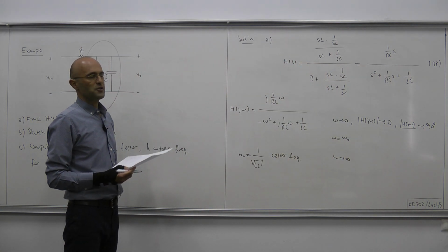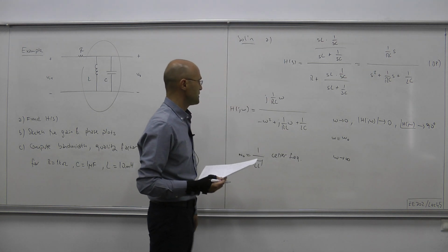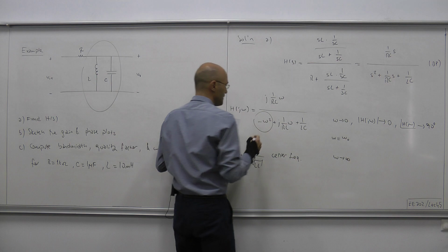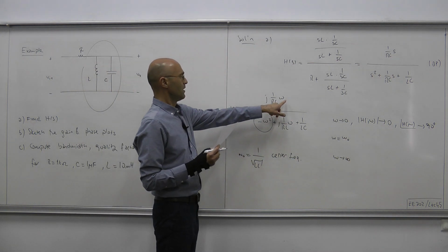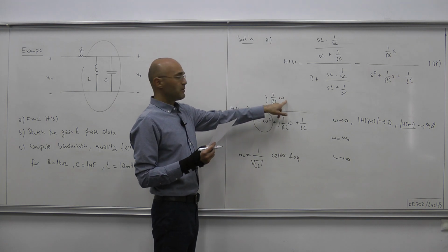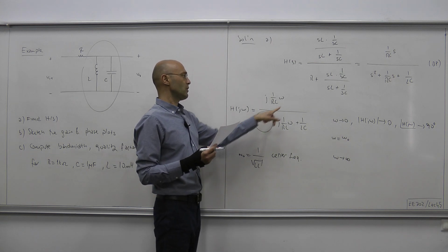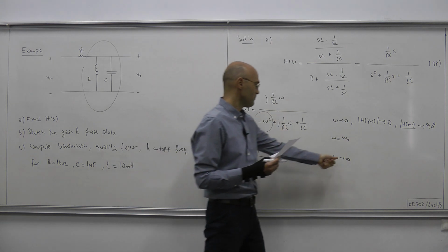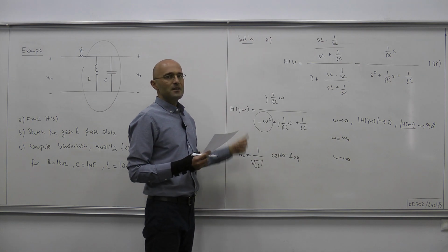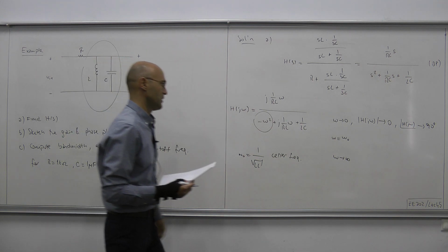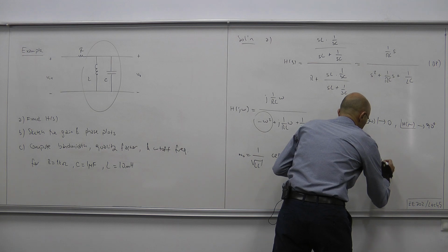Let's figure out the other end, the other tail. At high frequencies, this time this term dominates the denominator. Omega is also high, but this is a second order term, omega squared. Therefore, the magnitude of omega squared is much larger than the magnitude of omega when omega is large. That means the gain is again very insignificant at high frequencies. So H(j omega) tends to 0.